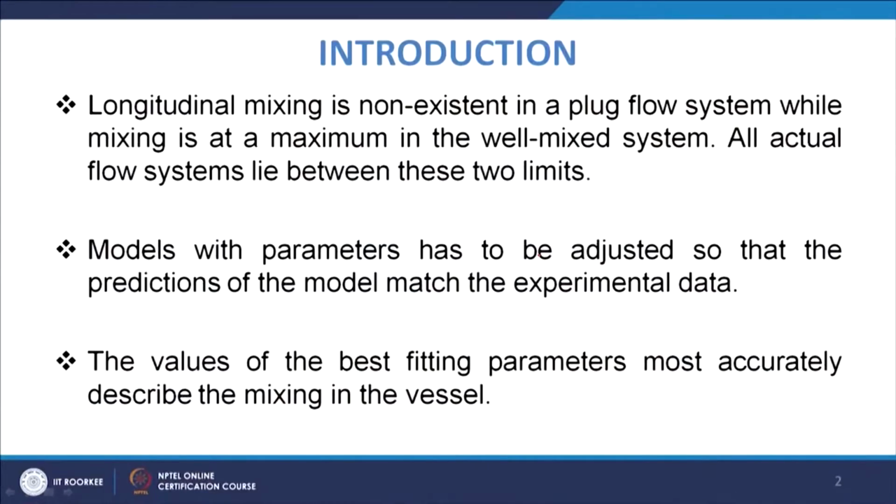In the ideal plug flow system, longitudinal mixing is non-existent. We have seen that it is a system in which there is no longitudinal mixing, and in the well mixed system the mixing is the maximum. These two are basically the two extremes, and the actual flow systems lie between these two limits.